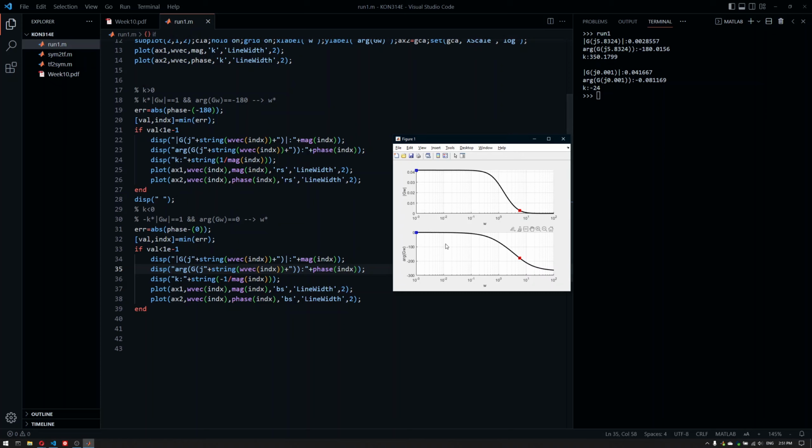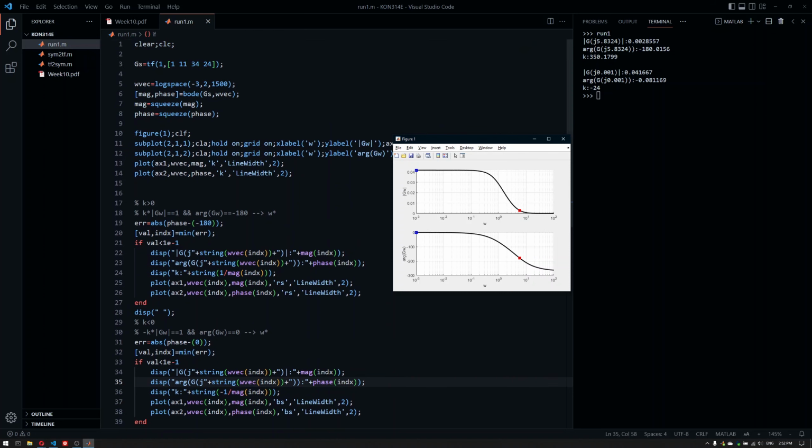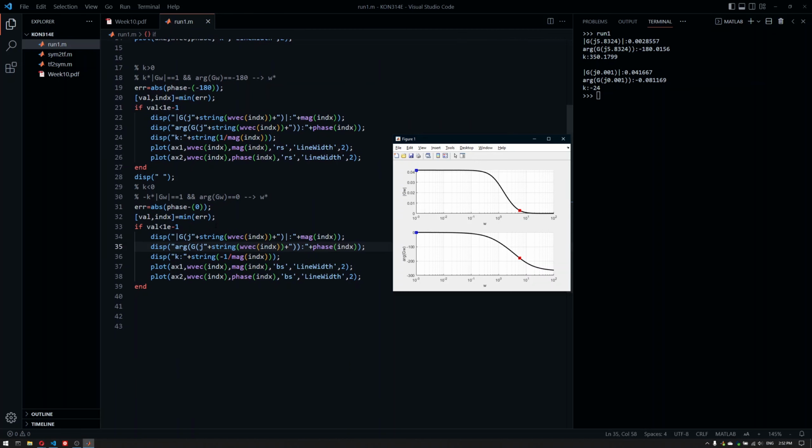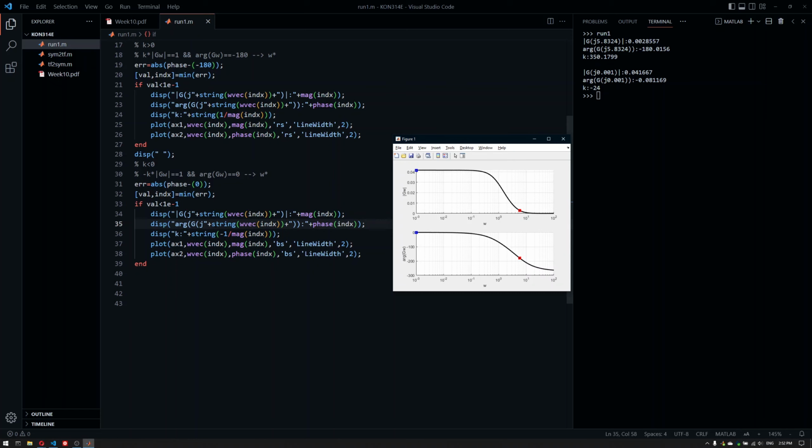Look for the phase 0 here, or the closest point to that. Look at the frequency. At that same frequency, read the gain or magnitude value. Take the inverse, and you also have a negative sign because you're looking for a negative bound. And you have the negative bound. I've coded it so that you might change the transfer function, and it will try to look up the best point that is suitable for us, so you can use it basically as a template.